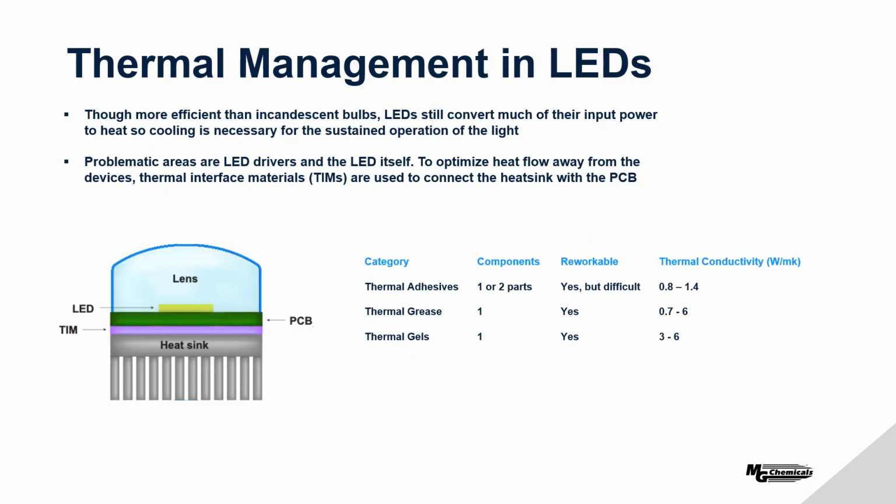Another issue within LEDs, of course, is thermal management. As I said before, it's a bit of a misconception that LEDs don't get that hot. They still convert much of their power to heat, so it's necessary to cool the LED to ensure that it does not overheat. Problematic areas are the LED driver and then the LED itself. So the design consideration here is to interface or mate the LED surface, or the heat generating surface, with a heat sink using a thermal interface material. And with that, we have several different options available.